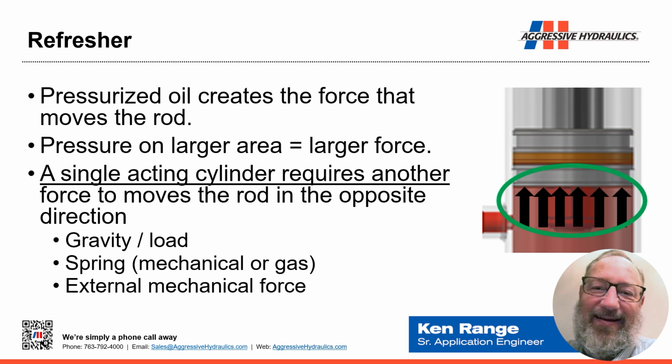If you recall, it's the pressurized oil that does the work inside the cylinder. The pressure of that oil on a certain surface area creates a force. The larger the area that pressure is applied to, the higher the force that's created. And because we're talking about telescopics that have different stage sizes, that point about the force created by the area it's applied to really plays an important role in these telescopic cylinders.